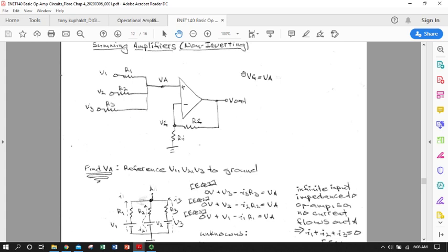Okay, so let's march through this and see how this compares to the inverting summing amplifier. Well, the first thing we can say is our feedback voltage point here, which is the input to the inverting terminal, VF, and we'll call it VF because it has the potential of V feedback by dint of the feedback fraction flowing through our resistor here. We defined that terminology back in chapter 3. We know that's going to be equal to V sub A because these two terminals have to have the same potential via our idealized assumptions. So V sub F equals V sub A.